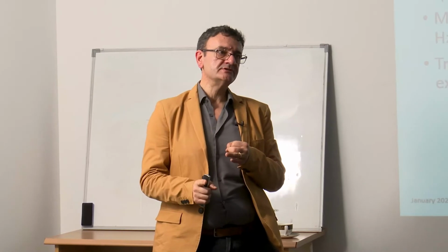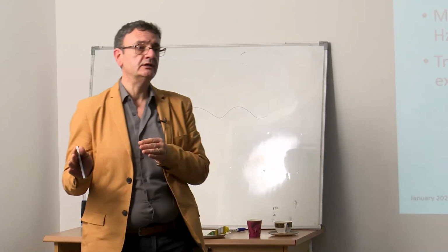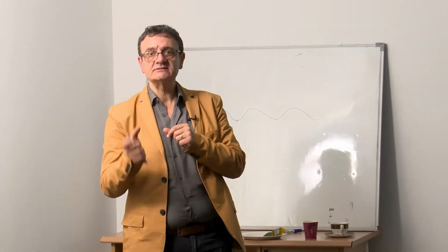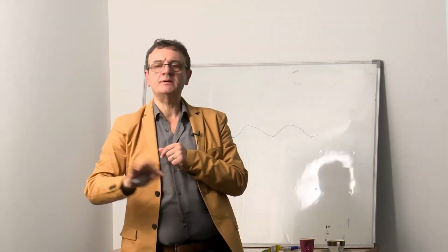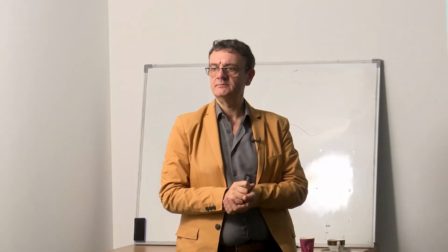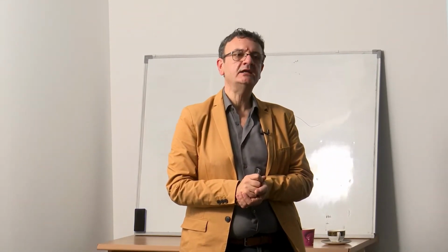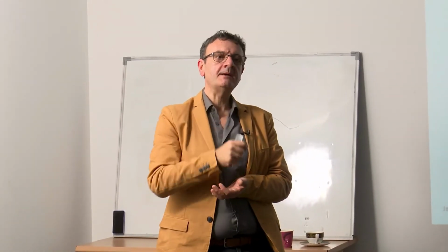Second, when you test it on site, using standards, you need to follow the exact ASTM standard methodology for testing. You can do that on site. However, there is flanking noise, and flanking noise is going to affect the STC rating of that system. Noise comes through the wall, through the parapet, through tubes, pipes, anywhere. So you cannot claim exactly the STC rating, because that's under strict lab conditions.